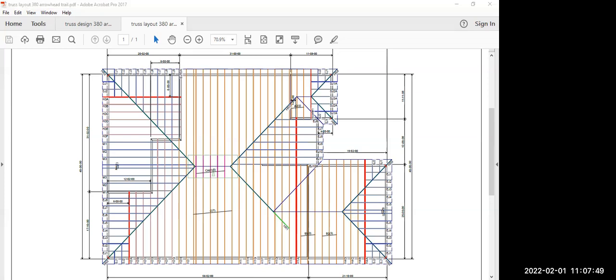Let me see, is this the same one? Let me show it to you. Notice in this case, right where that landed, in my case it actually happened to land right on the top of a door. So the weight is centered over the top of a door. That's going to transfer the weight over to this side and over to that side. So I basically just had to put a note there that those 2 studs holding up that beam that goes over the top of the door need to be there in order to support truss H1A.